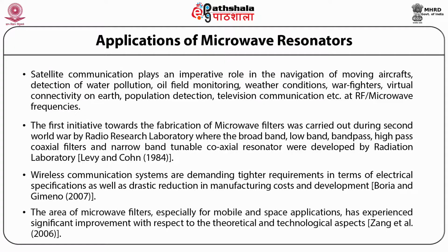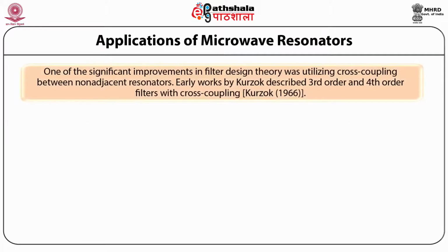So the area of microwave filters, especially for mobile and space applications, has experienced significant improvement with respect to the theoretical and technological aspects. One of the significant improvements in filter design theory was utilizing cross-coupling between the non-adjacent resonators.